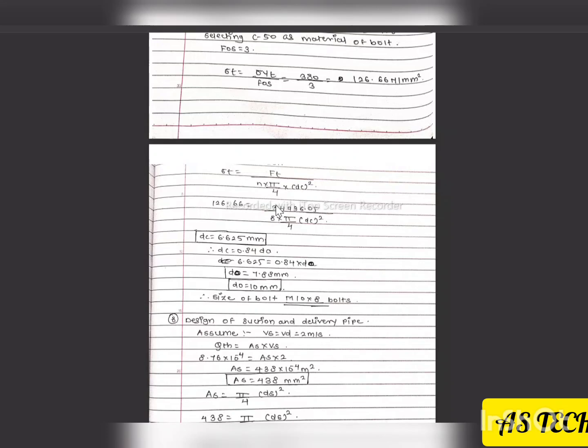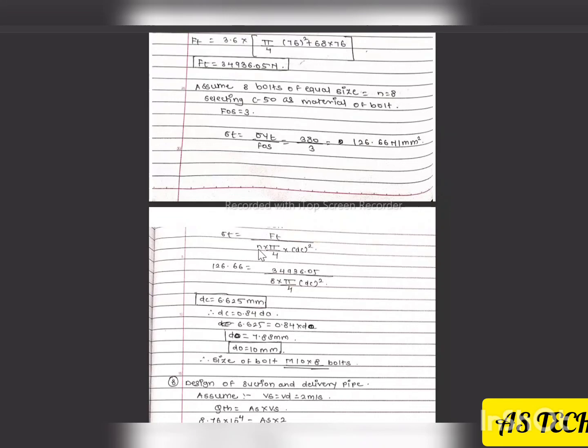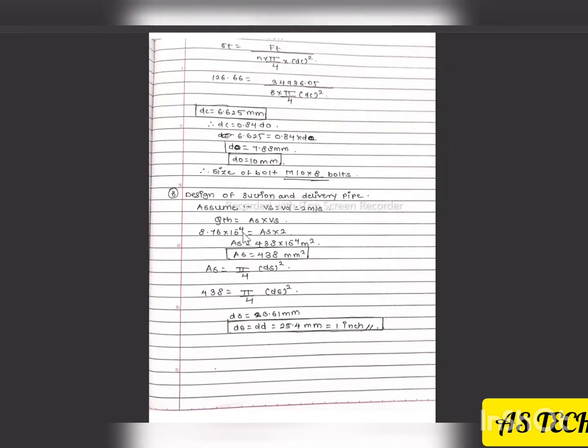Now to calculate DC square, core diameter of a bolt, sigma T equals FT upon N, number of bolts, into pi by 4 into DC square. Put all the values to calculate DC. We get the value of DC. Now DC equals 0.84 into DO, where DO is outer diameter of a bolt. So this is the standard formula. Put the value of DC and calculate DO, outer diameter of a bolt. And the size of bolt is M10. This is M10, outer diameter of bolt, into number of bolts, which is 8 bolts.